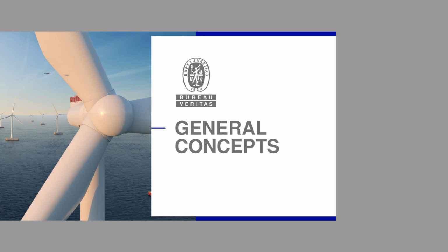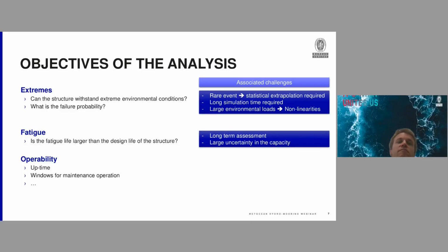Hello, everyone. So we will start with a few general concepts that are linked to floating structures. First, what are the objectives of analysis? We want the structure to be safe with regards to extremes, that is to say, is the structure able to withstand extreme environmental conditions, and what is the failure probability. We also want to ensure that the structural fatigue life of the units is large enough, and of course larger than its design life. You can also have questions about the operability of the units, that is to say, what is the uptime, what is the available window for maintenance or operation.